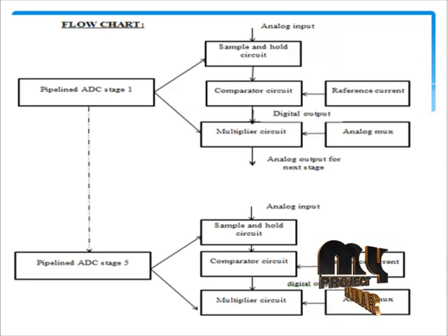The analog-to-digital converter uses a sample and hold amplifier to take the input analog signals. As the input frequency increases, the power and noise of the ADC may increase, because an SHA-less architecture has difficulty achieving high SFDR for IF sampling applications with fast, challenging input signals.